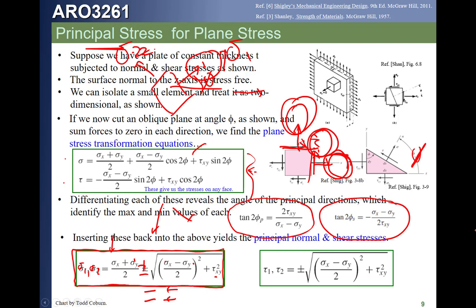However, we also can look at this part of the equation and say, oh, that's actually the same piece that we get by plugging in this other angle. That's actually the max shear stress. So this looks like one equation, but look, we got a plus and a minus, which really is two equations. So this one has four equations buried in it.